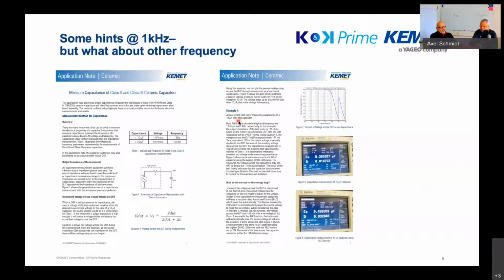What actually happens is that there's a voltage divider between the source impedance of your device, the Bode 100, and the capacitor. So the voltage splits up, and I'll come to that in more detail in the next slide. But this measurement, what you see on this Agilent or Keysight or whatever they're named right now, is actually done at 1 kilohertz, which is not your application switching frequency. That was the question we dug into, and we are really curious about what really happens in your circuit.